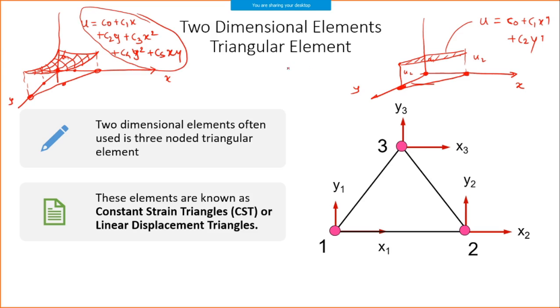So here, if my displacement is linear, and I take a derivative of this displacement, I'll get a strain, and this strain, du by dx, becomes constant. That's what is called a constant strain, because the strain anywhere within this entire element remains constant. If I look at this other element, the displacement is second order.